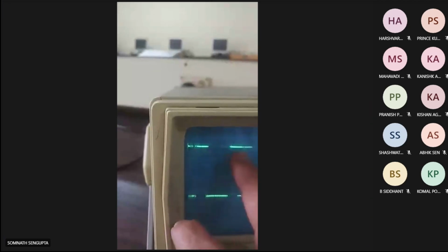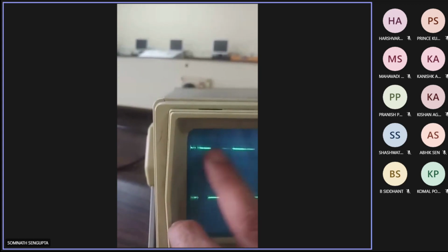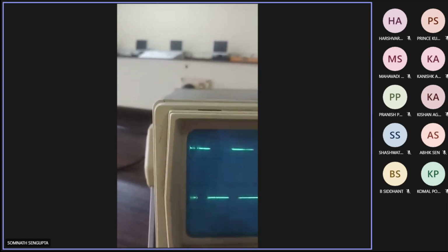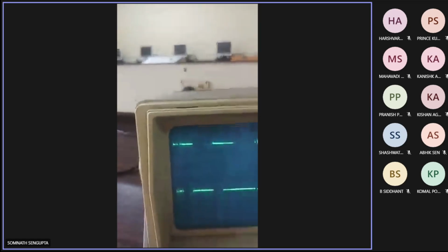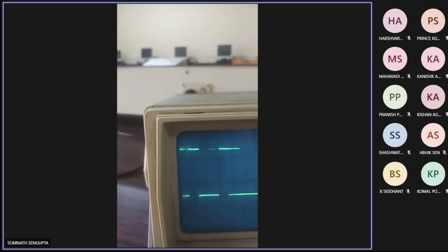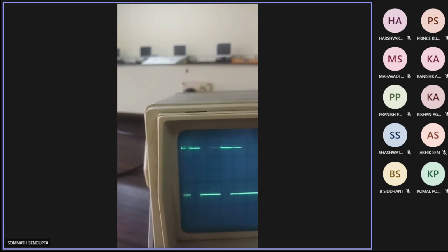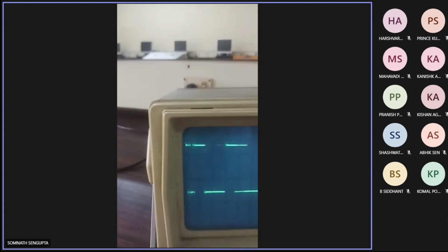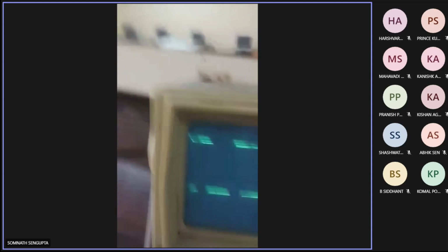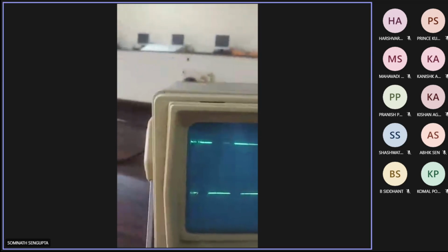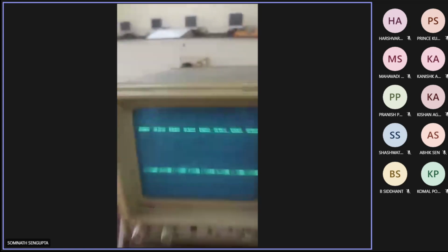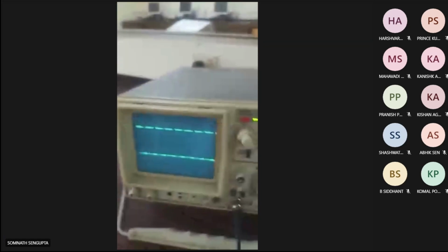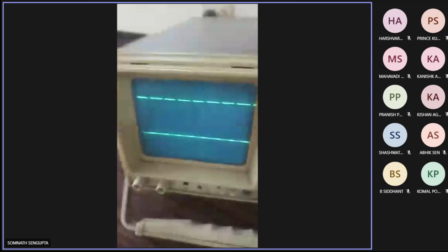If you measure the duration of the time difference between these two, then you can measure the frame period, because they are situated exactly with a time difference of one frame duration. One sitting is one frame, another sitting is the other frame. Another data you will see in another frame. This way it is calculated, and that comes to be 125 microsecond.